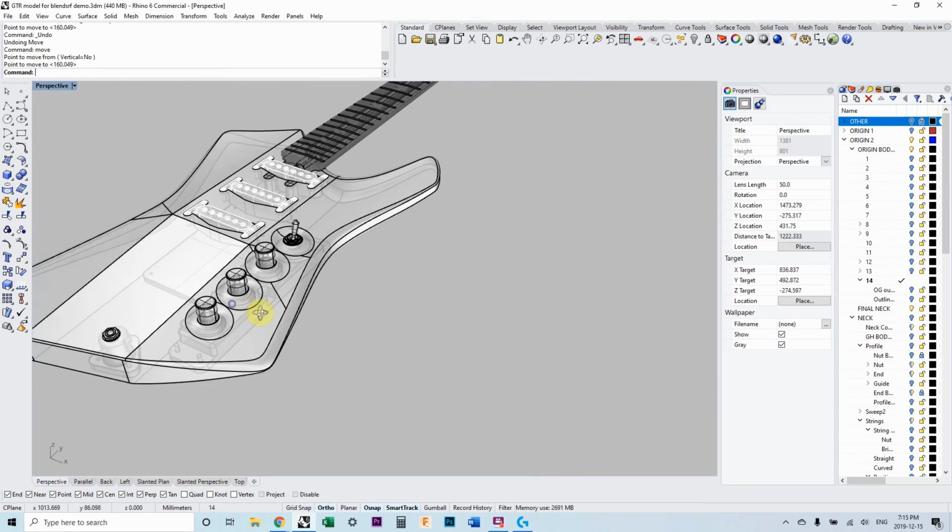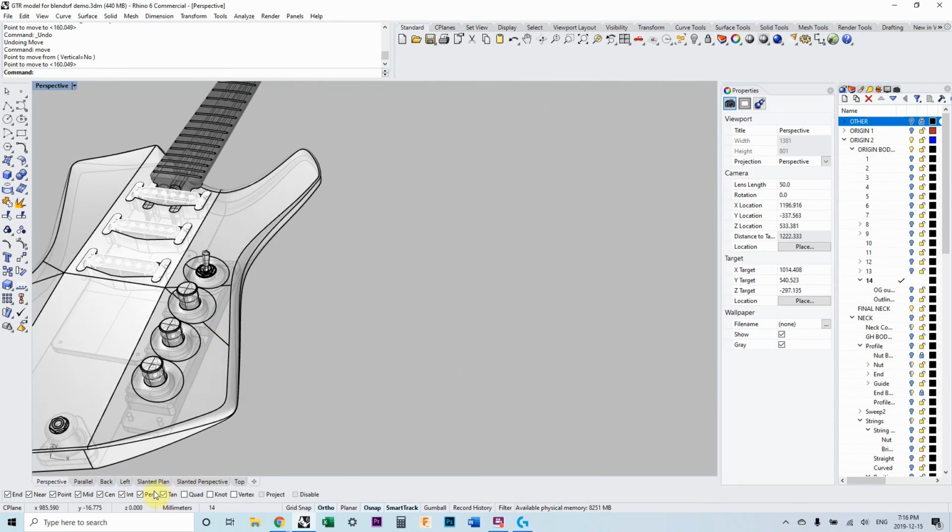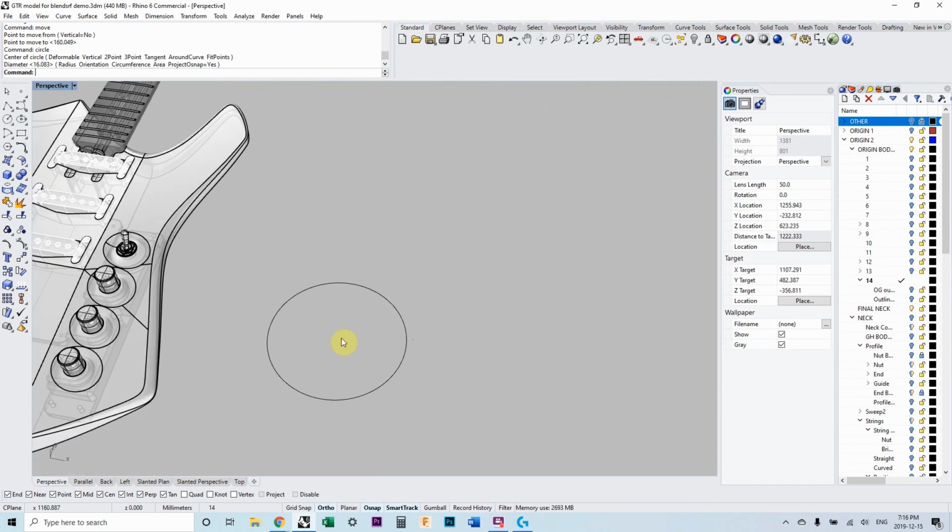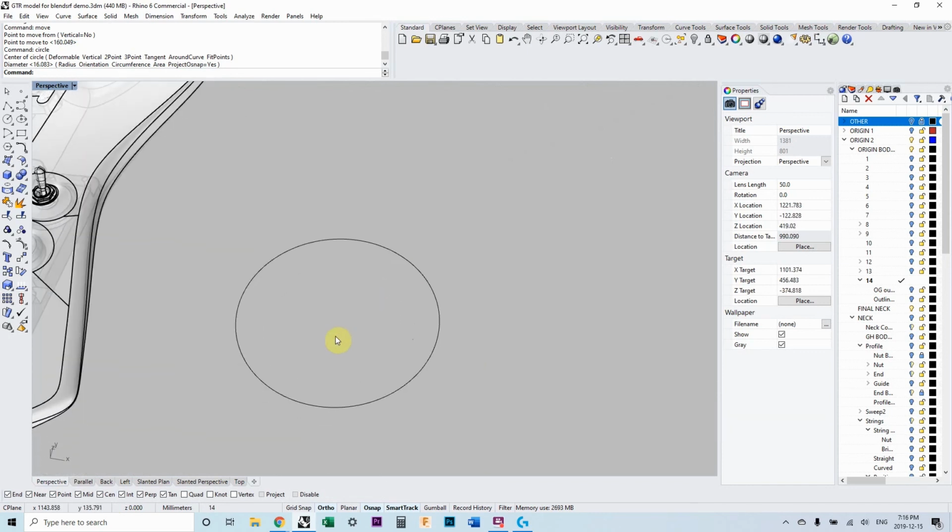And the other thing that we have here, another hidden feature, if you hold Control, you can see that there's a little hidden panel down here. So let's say this is sort of a unique object snap feature. Let's say we wanted to make a line where we want a point that is tangent to some part of this circle.